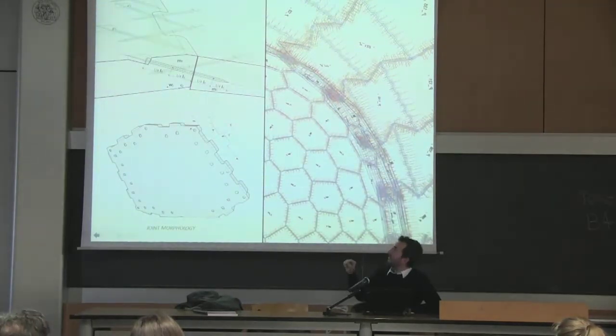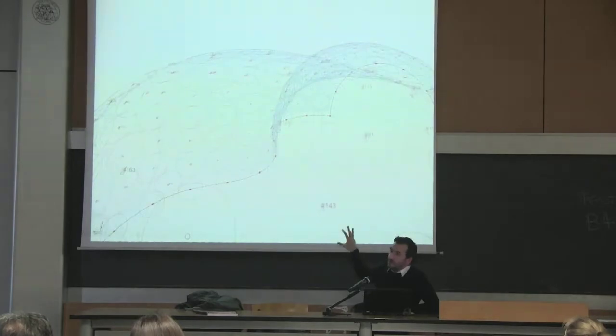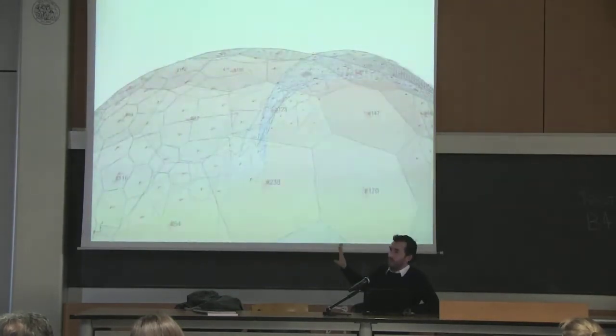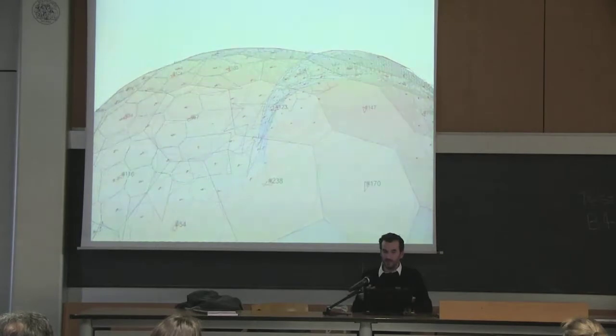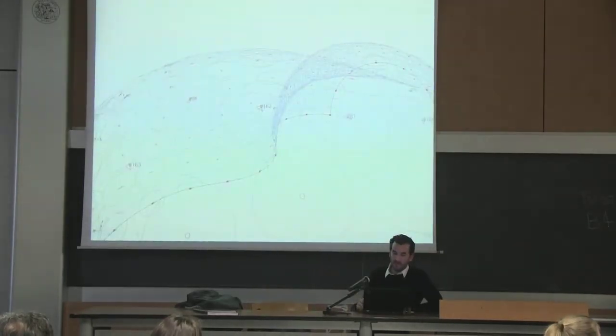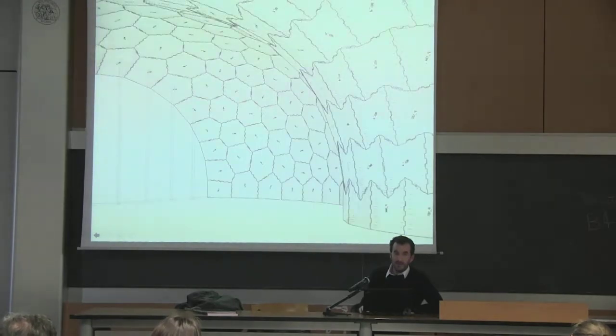and especially it knows about the constraints of the building code and the building standards that need to be fulfilled, especially on the screw connection level, which are crucial to get it through proof engineering. And with all that knowledge, the blades begin to venture around and find their own configuration by themselves. So it's really that the blades themselves explore the space of the fabricable and find a suitable, structural, and producible condition. And this is actually showing that this works with this distinctive transition of blade geometry. And it's also important to understand that this has significant architectural consequences because the timber is what you see on the inside.